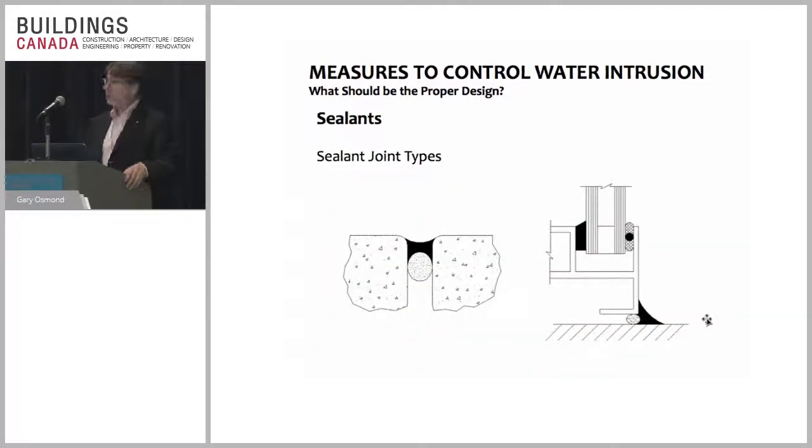There were actually two shots here. One was showing fixed joints or weather seals, and then there's this shot that was nicely sliding on top that shows joints that move. It's a very important consideration in looking and picking sealants, because again, there's fixed joints that don't move, so dynamic joints versus static joints. Did you pick the right sealant? Does it have the elongation? Is it the modulus you're looking for?